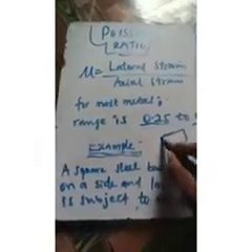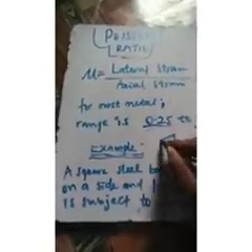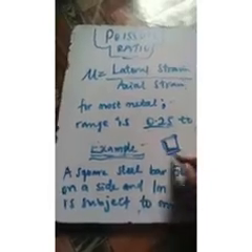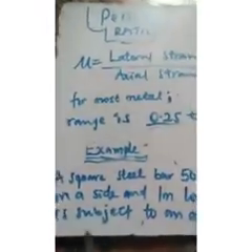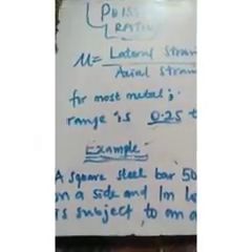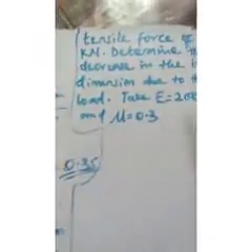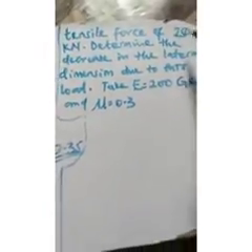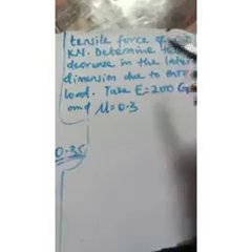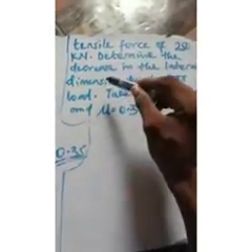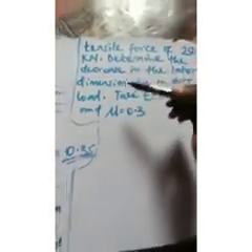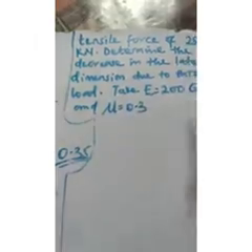A square, sorry, a square is like this, has both lengths equal, and a single side is 50 millimeter, and 1 meter long, is subject to an axial tensile force of 250 kilonewton. Determine the decrease in lateral dimension. So decrease in lateral dimension talks about lateral strain due to this load.